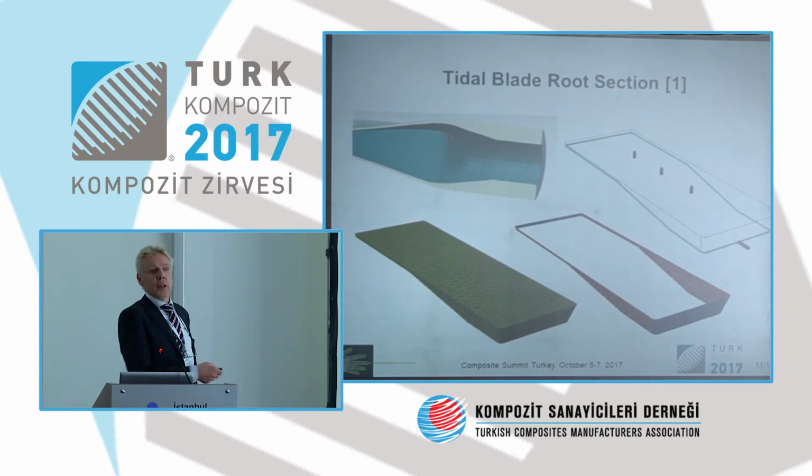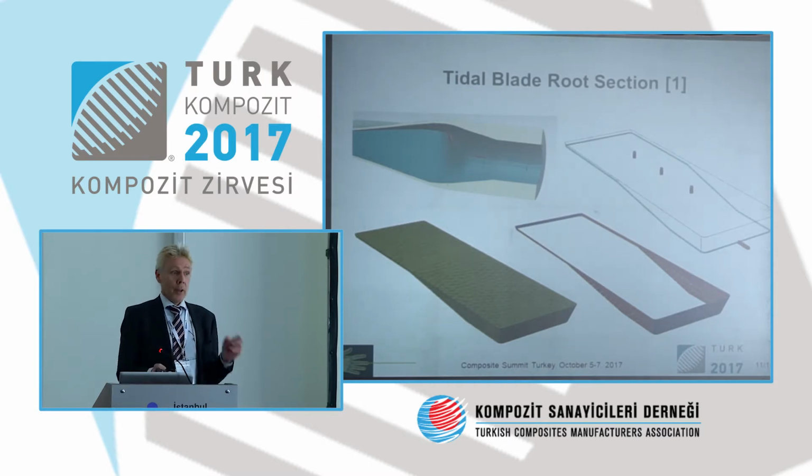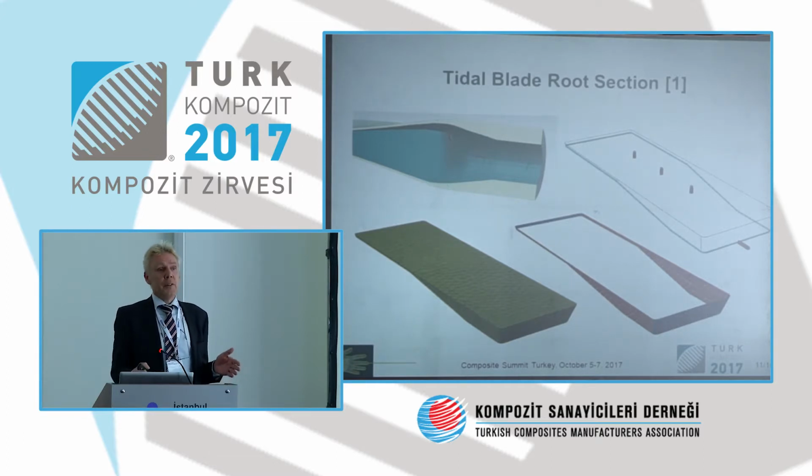Now, the model, and I showed you at the start of this presentation, consists of the reinforcement. This is carbon fiber, modeled with 3D elements. We have surfaces around the model to model the gap between the preform and the mold, because if you have a very thick preform, it doesn't fit exactly, and even 1/10 of a millimeter gives you a lot of resin flow. So you need to take this into account.